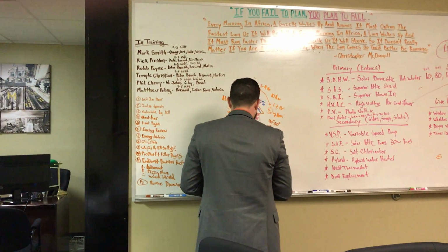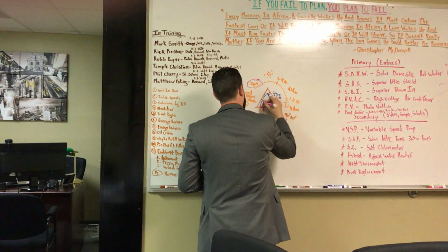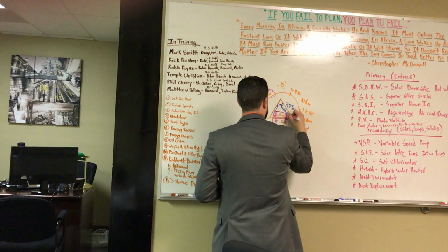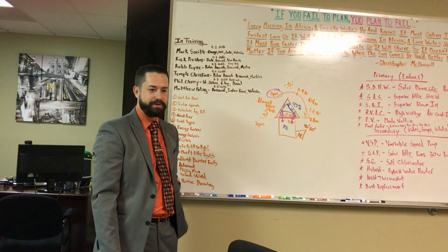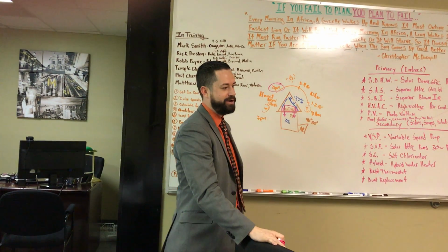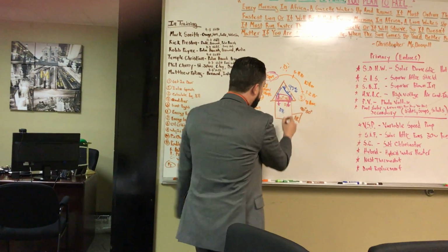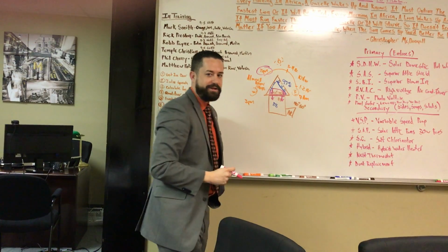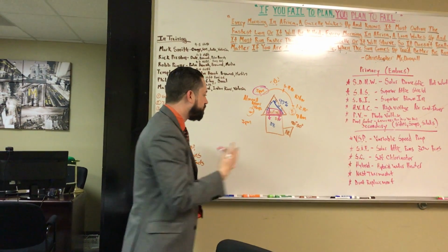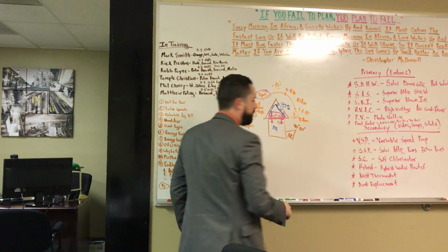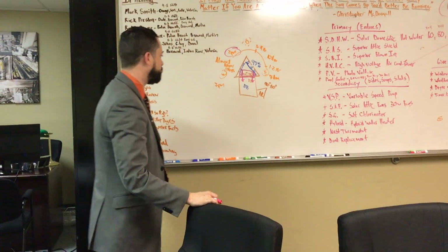Now also keep in mind, all of your AC ductwork runs through the attic. So what you're doing is taking 50-degree cold air, pumping it through a 150-degree attic space before you funnel it into your living area. You end up losing 10 or 15 degrees of that cold air by the time it actually makes its way into your house. You see how reflective insulation will reduce that process, reduce the strain that you're putting on your AC system? Does that make sense, Matt? It does. Absolutely.